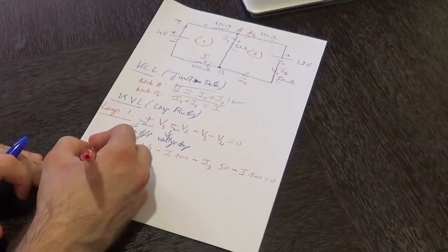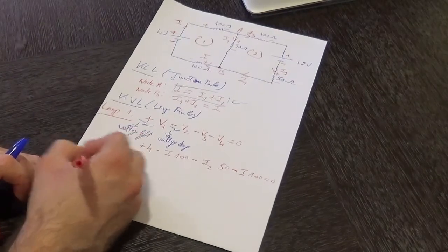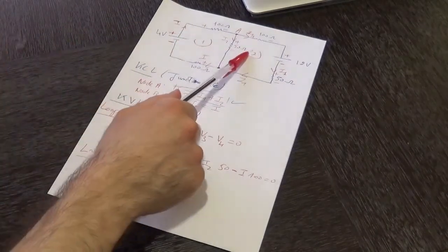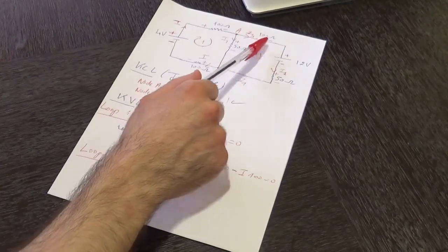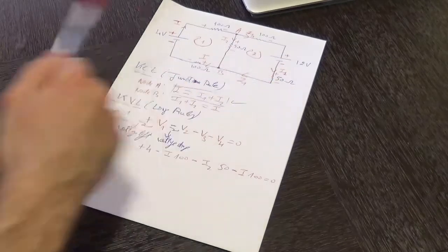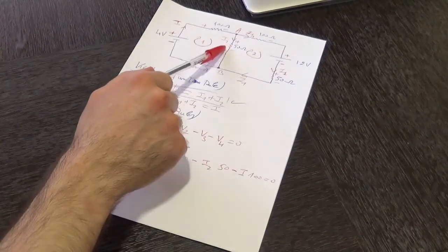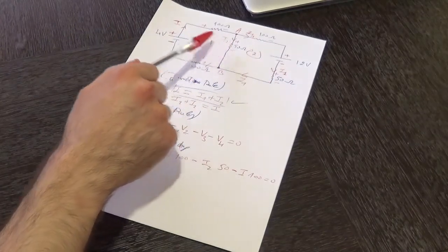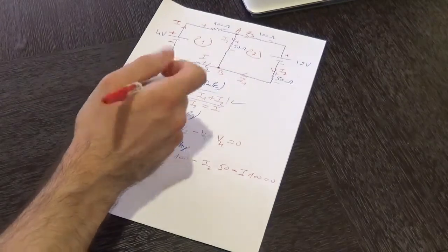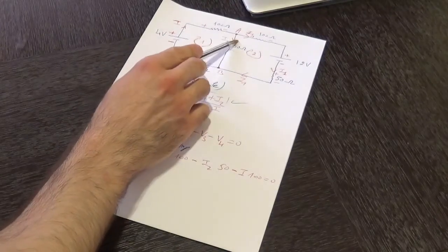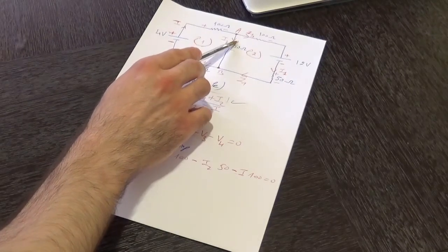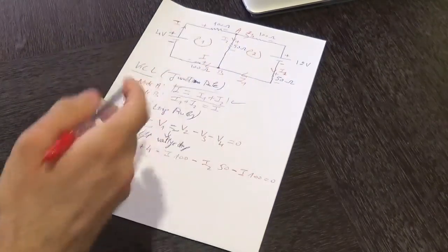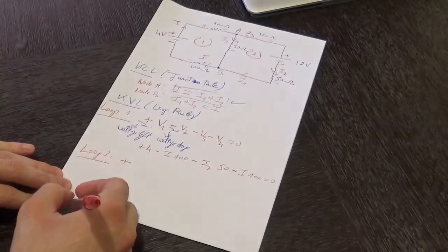Now the equation for loop number 2. Again, for loop number 2, we are moving clockwise. We are starting at that resistor, moving on to the 100, to the battery, and then to that final resistor. Starting at that first resistor, 50 ohm, we are crossing now from negative to positive, meaning from a low voltage point to a high voltage point. Therefore, we have a voltage lift, which we indicate with a positive sign. So it's plus